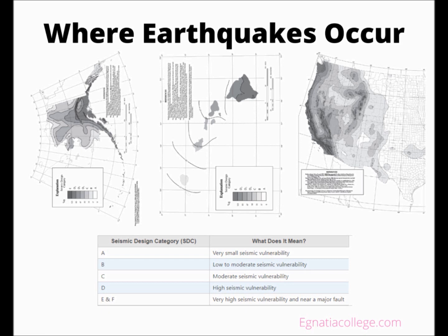Dead loads, the weight of the building materials. Live loads, loads that change or move around the building, such as people and furniture. Dynamic loads, loads that produce varying amounts of force, such as snow, wind, or earthquakes. Seismic loads. Many of the methods used to resist earthquake damage will also prevent damage from strong winds.